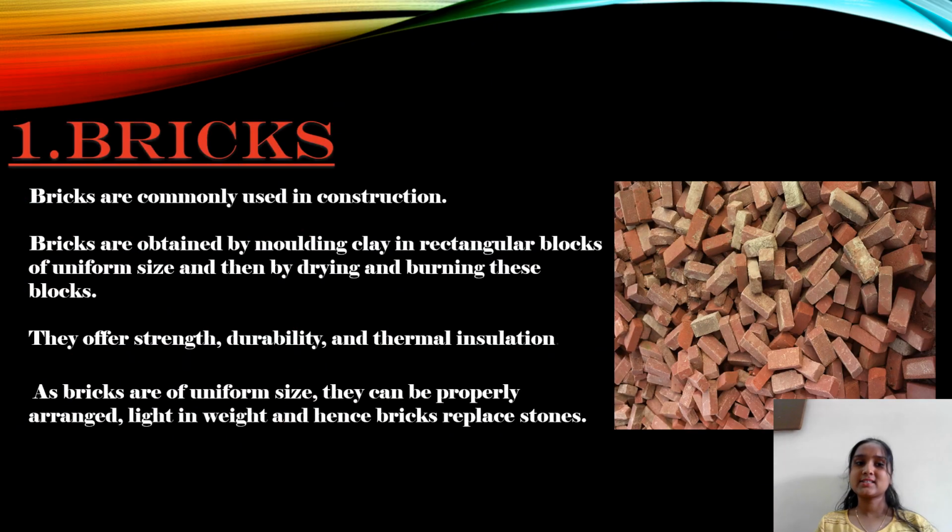First one is bricks. Commonly, bricks are used for construction. How are bricks obtained? These bricks are obtained by molding clay in rectangular blocks of uniform size and then drying and burning these blocks. They offer strength, durability and thermal insulation. As bricks are of uniform size, they can be properly arranged, and being light in weight, bricks replace stones.